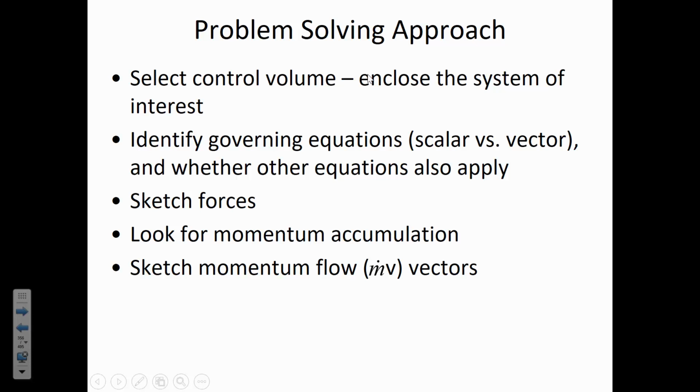So the jet, as it's changing direction, is pushing on the plate to the right, and the plate is pushing on the jet to the left, and then the system is in equilibrium if those two forces are equal. So as far as sketching the system, you'd need to put the control surfaces around where some change occurs, like where there's an interaction between the jet and some deflector.